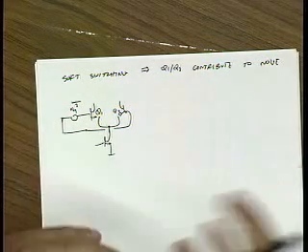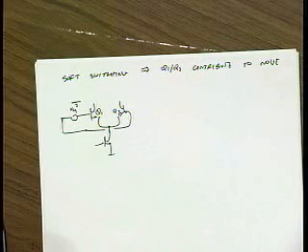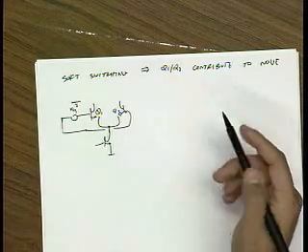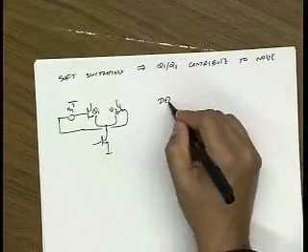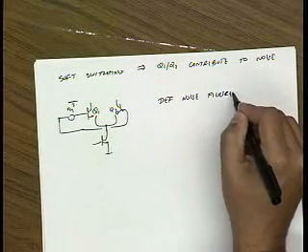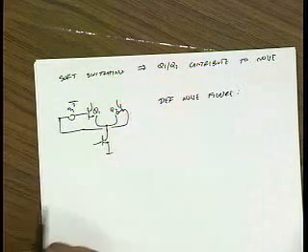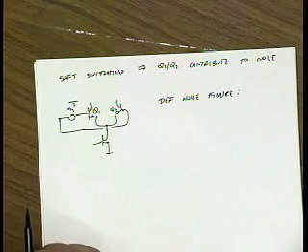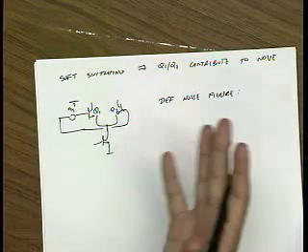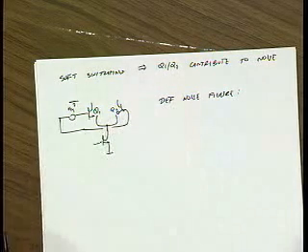Okay? Question? So in general, when you have two input ports like this, how do you characterize noise figure? You have two different noise figures for different inputs? Well, the noise figure, the way we define it, so the definition of the noise figure is actually a little bit complicated. And there's two definitions for mixers. One is the IEEE definition, and one is kind of a microwave definition. And it's because of the fact that there's the image noise.